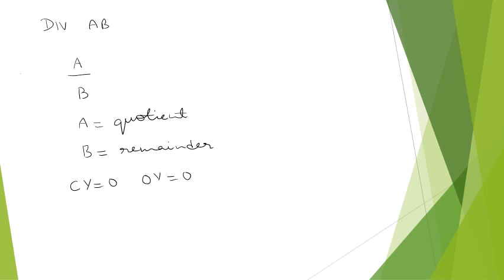Whereas if register B has the content 00 in it, then after the division operation, the values returned to the accumulator and register B will be undefined, and the overflow flag will be set, whereas the carry flag will be cleared. The overflow flag will be set to indicate that the result is invalid, since the divisor, that is register B, has the value 00.